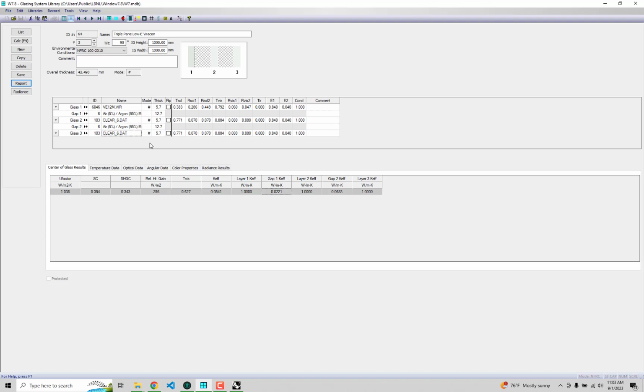Because more often than not in practice, we tended to use a code baseline for most of the constructions of the building. Working in Boston, it has a very modern energy code. I think it's right now using the latest version of ASHRAE 90.1, the 2019 version. So a lot of the constructions, at least the opaque constructions, have very thick insulation. And while you could increase the insulation, you weren't necessarily getting a lot of benefit from that. However, most of the window constructions in the latest code were still at the level where you can get away with a double pane construction.